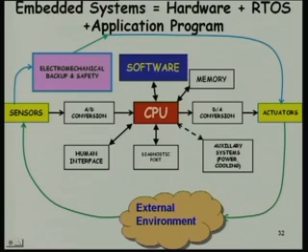Okay, it is a type of electrically erasable programmable read-only memory. So, EEPROM, but EEPROM existed for a long time. We did not have flash memory at that time, is it not? EEPROM is not really flash memory, because these had restrictions on the storage. You write bitwise there and it required high voltage,